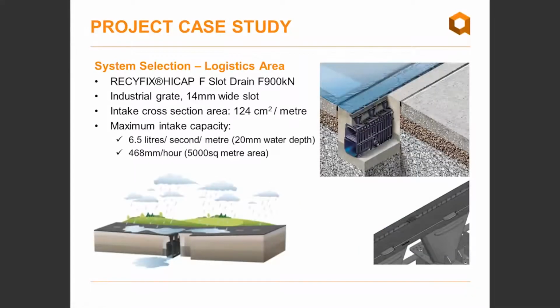The intake capacity, some people feel that with these longitudinal slot type systems, these slot drain systems, that the intake capacity might be less, but in fact the intake capacity is very high with these systems. This trench drain that we chose for this particular area had a 40 millimetre wide slot.